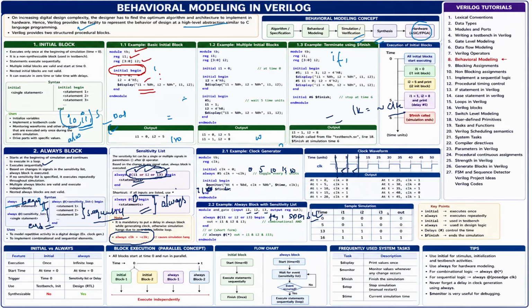Inside that you can also assign any variables, like I1 equal to 4'b1010. Suppose I am mentioning 3 down to 0 for I1 also, then 4'b1010 data we are giving. And I2 is also 4'b1101 data we are giving. Based on that, it will do the operations and then display the values. See, I am giving the value in binary format, but I am displaying in hexadecimal format. It will convert and give the data in hexadecimal format only.